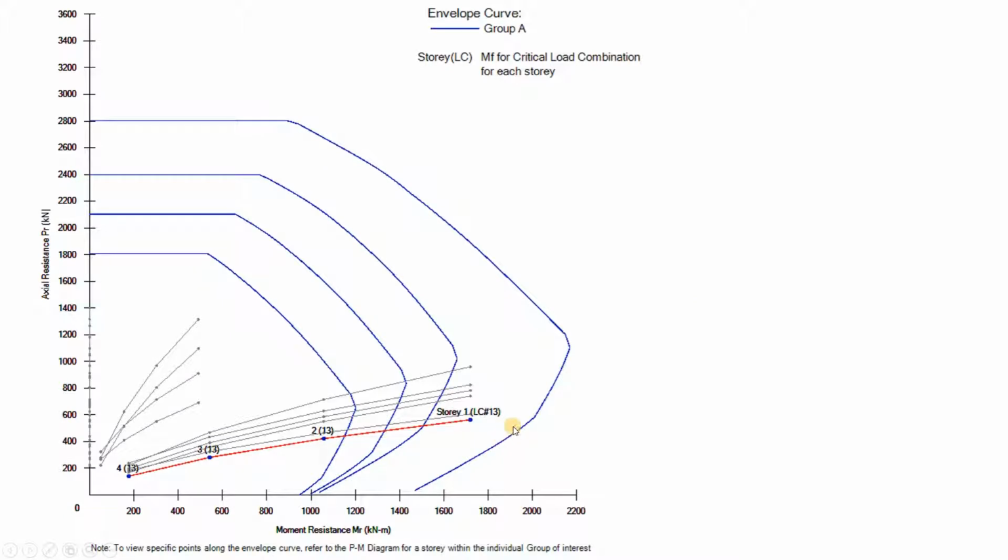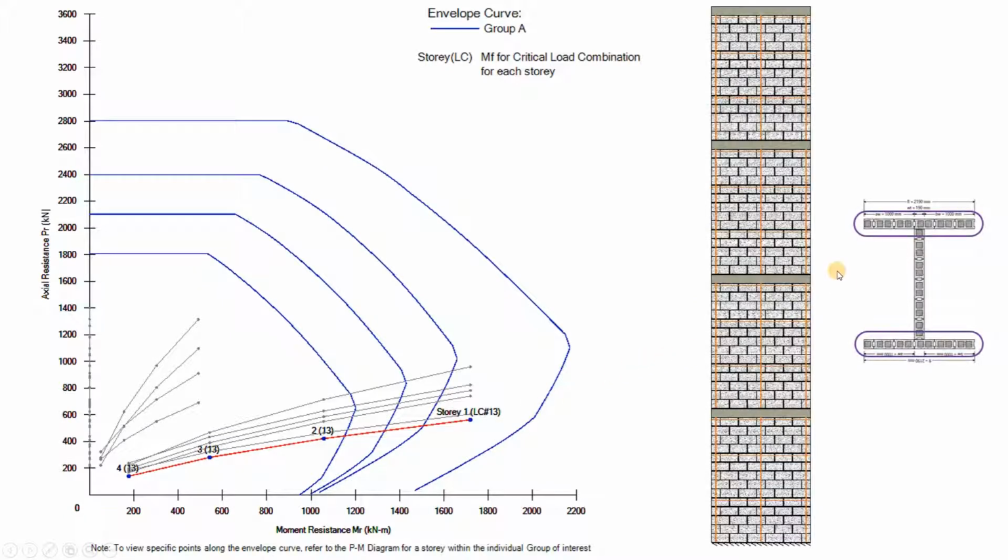Let's look back at our diagram. We have these different envelope curves that show up there. If I go back and instead of looking at the regular cross-section or the elevation that we're used to, we're looking at the flange, what I'm going to do here is highlight the area that intersects with the web. So here's the shear wall web, and these are the flanges. Now if I overlay those effective flange areas that we calculated, you'll see as we work our way down, we have more and more of our flange that's effective.